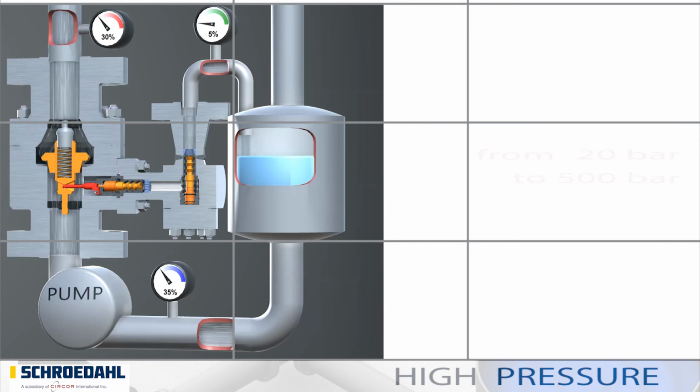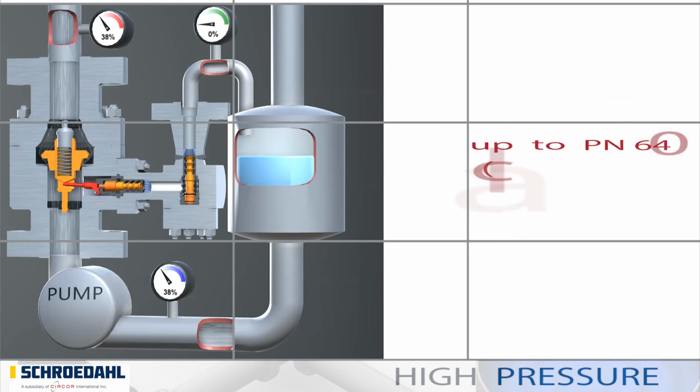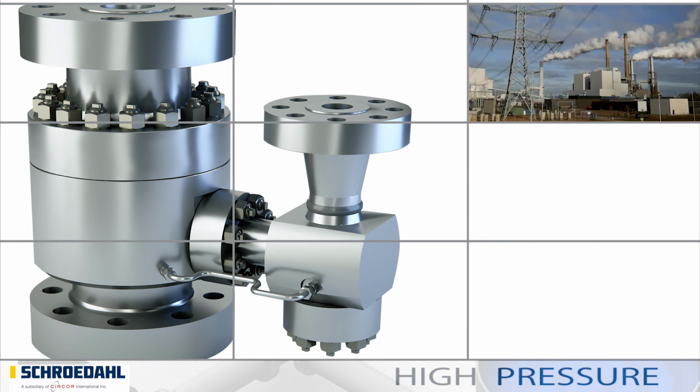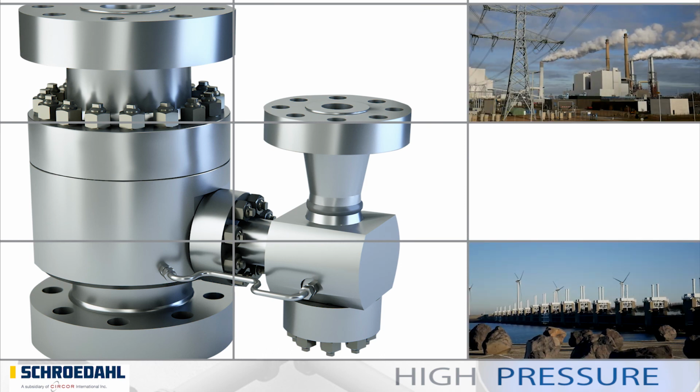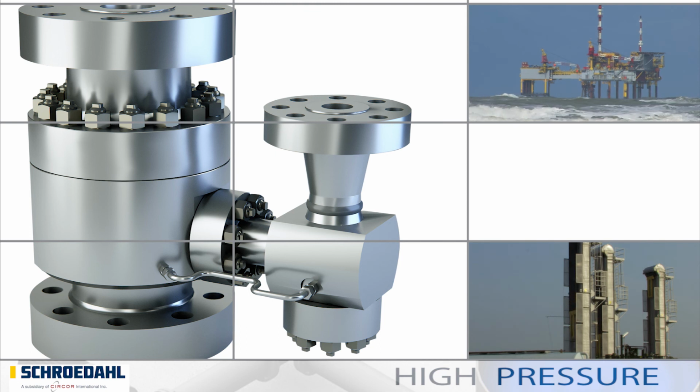The nominal width range extends from DN80 to DN350. With the MRK, the pressure stage is even designed for up to PN640. The MRK valve is the perfect solution for all feedwater applications that are mostly operated in the partial load range. However, an application for seawater injection pumps on oil platforms is also conceivable.